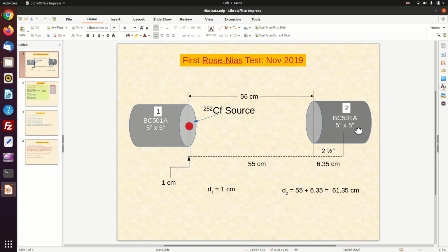So for the two types of pulses, gamma rays and neutrons, we make use of that and try to choose those which have the pulse shape as expected for neutrons rather than the pulse shape which is broader for gamma rays. So we take out the pulse shape signal. This is done by some electronic processing called the pulse shape module, not shown here.